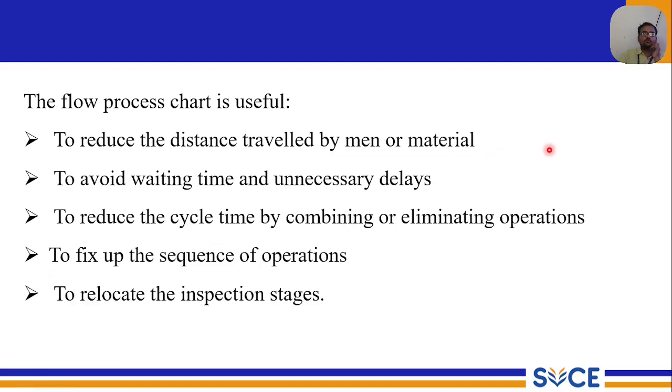How useful is your flow process chart? It helps you to reduce the distance traveled by the men or material. That is the key important aspect of method study. I keep on repeating the same point because method study is the only technique which will consider the worker as well as the process when studying equipment or methodology. Other techniques usually consider only the process.